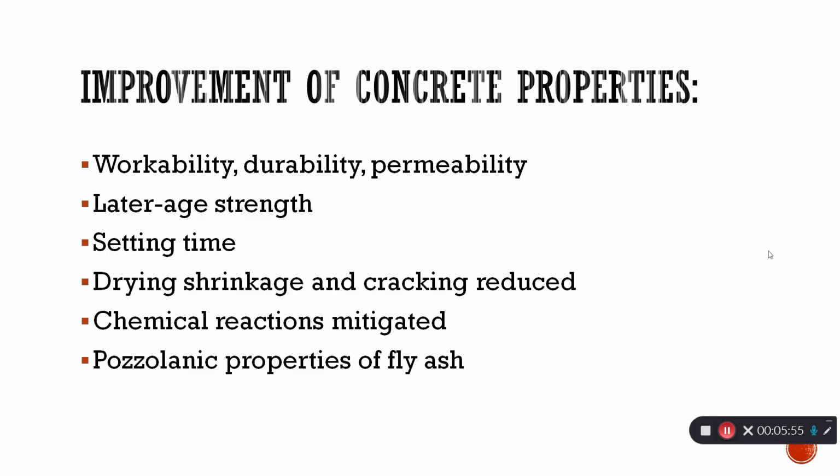Durability is improved primarily because the permeability is reduced and the durability is enhanced by its resistance to chemical attacks. Permeability is improved because of the number and size of interconnected pores in the concrete matrix. Later age strength is improved through a pozzolanic reaction. This pozzolanic reaction will continue over the life of the concrete, and this makes the concrete matrix denser and increases its strength and durability at later ages compared to Portland cement with no supplementary cementitious materials included.